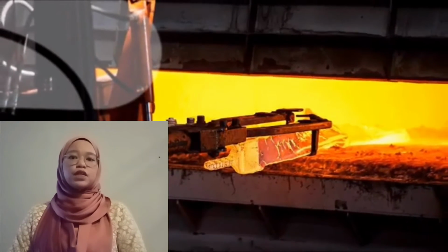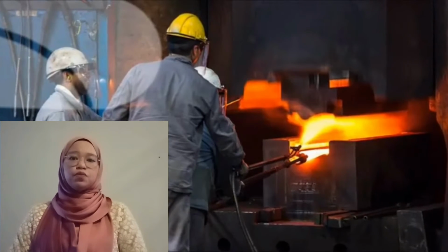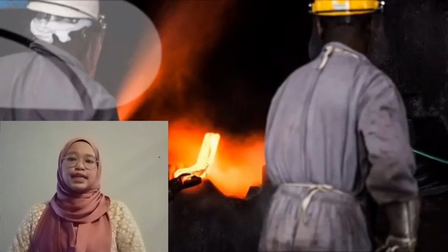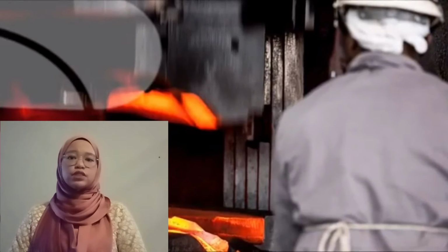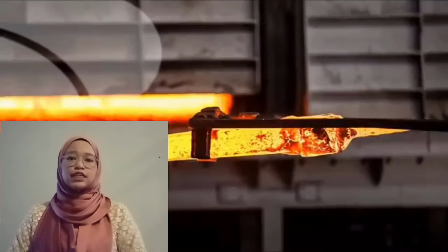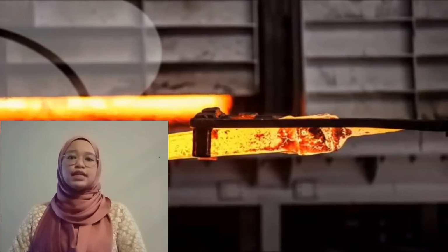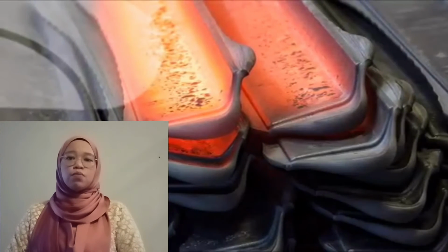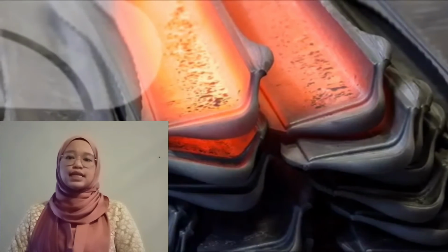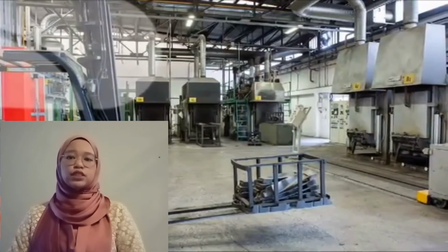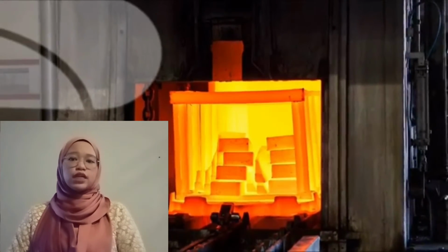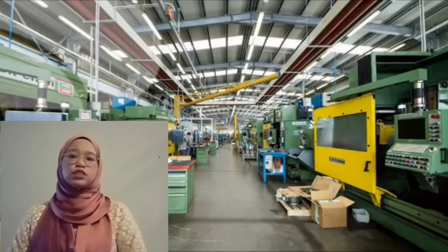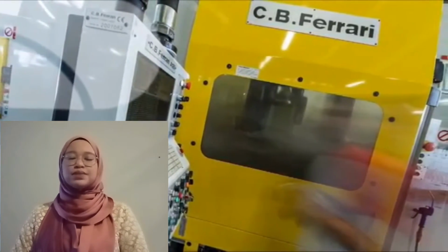In the process of manufacturing this blade, we use closed die forging. That is, a force is brought to bear on two or more die halves having the finished shape such that the metal is deformed in the cavity between them. Producing blades with the forging method is hard because of the high ratio of forging surface to volume. That is why the important elements of technological process planning are adequate tool design and ideal preform shape selection.